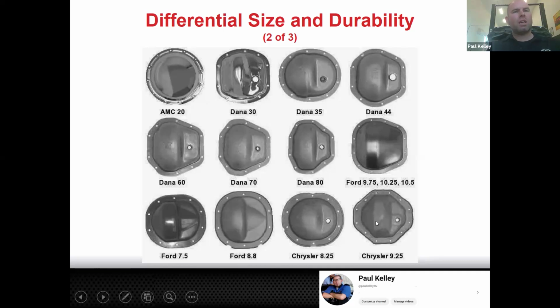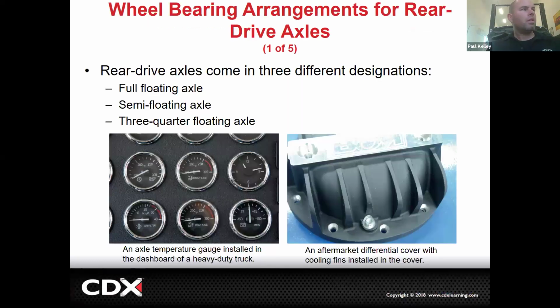Sometimes Chrysler was doing that too. A lot of the Chrysler stuff, Dana makes them, so you just go by the Dana. A lot of times with the Dana ones, you could look at the cover, or sometimes it's stamped on there, but sometimes it's hard to find. If it's pretty clean, you can find the stamp pretty easily, but it's not on the cover. Normally it's on the housing. All right, so there's a lot of info there on differential ID, but so far so good.